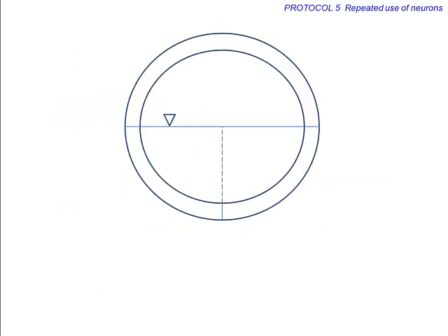For the same problem, calculate the resultant hydrostatic force on the curved surface indicated. In this case, only the weight of the fluid is acting on the surface, as the horizontal forces will cancel each other due to the axis of symmetry.